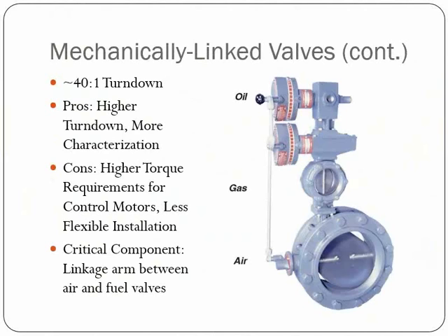So you have 2 points of characterization there on the air, but then as you adjust your gas up and down, you have those screws within your screw carrier assembly that allow your fine tuning and fine adjustments. But your air valve in this example, you really only have 2 points of adjustment.